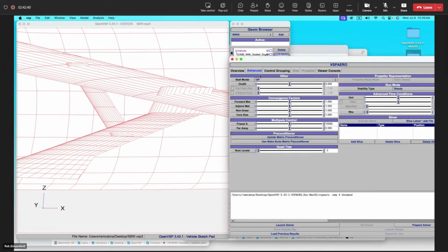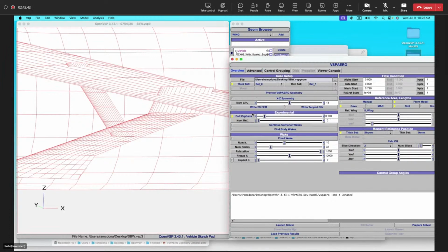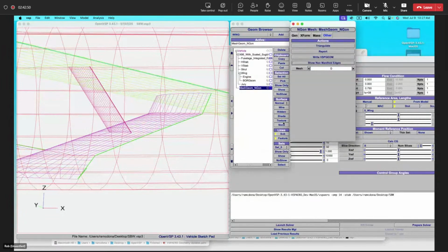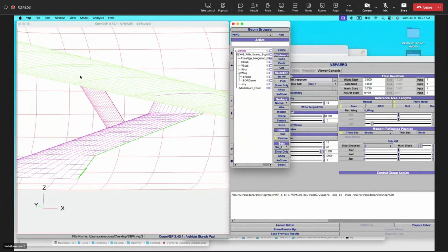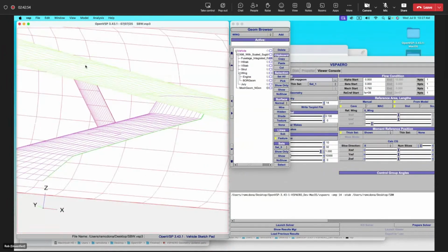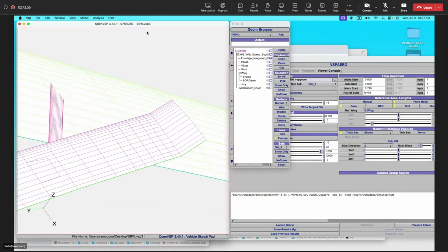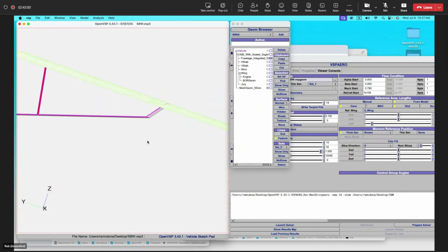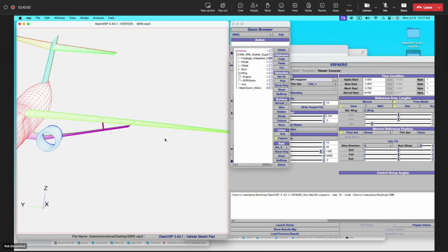And so that's what the Cull Orphans option is all about. When I prepare that solver, we're going to go through and do that intersection, but then we'll trim and throw away those little remnants. So we have that kind of an intersection that is more likely what you want in that case.